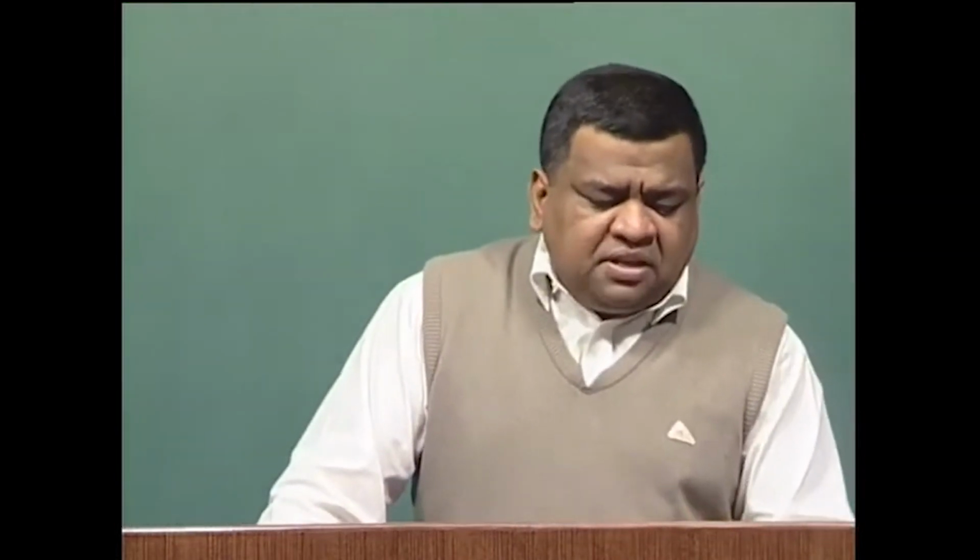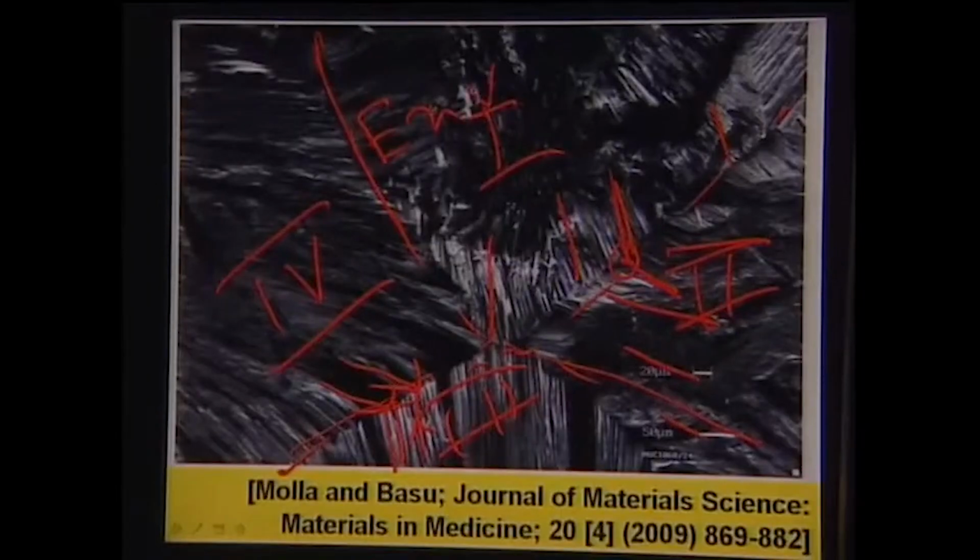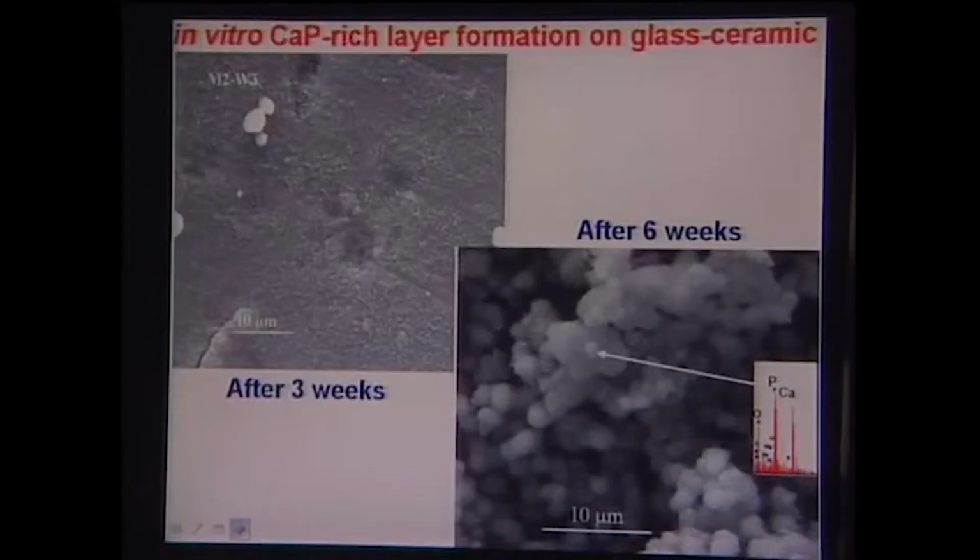Now, if you go back to the introductory slides where I told you that these glass ceramics really provide a good opportunity to develop different types of microstructure by changing either the base glass composition or the heat treatment conditions. In this case, you are getting the envelope type of crystals. In another case, I have shown you that you can get interlocked mica type of crystals. In another case, you have seen cabbage shaped crystals. So, all different kinds of crystal morphology are possible in similar glass ceramic compositions just by adopting different heat treatment conditions. So, that is the major message I wanted to share with you.